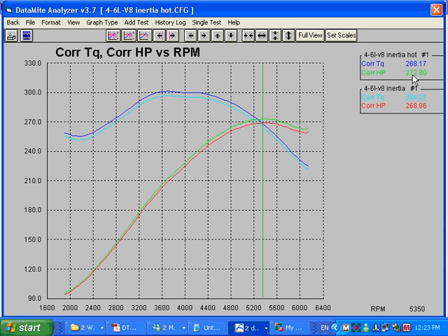One thing that can make the air temperature off, a little discussion on weather, is if you use our internal weather station, the temperature at the box, which is actually inside the box, there's a circulating fan to make it fast responding, but it can be different than what's over at the engine. You might have exhaust heat, all sorts of things could be different over at the engine. And the temperatures could be significantly different. So it is definitely more accurate to actually measure the temperature over at the engine.